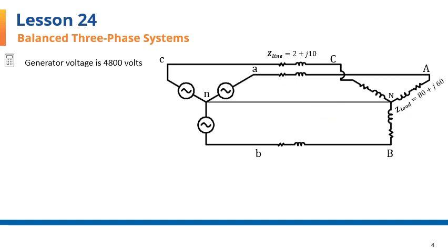When the voltage of a three-phase system is given absent any other information, it should be taken to be the line-to-line voltage, and of course the value is always given as an RMS value. The generator should be assumed to be generating positive sequence voltages unless it's specified to have been set up as a negative sequence generator.